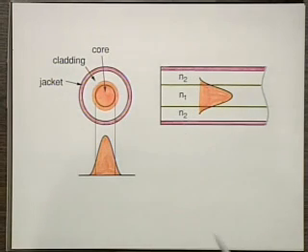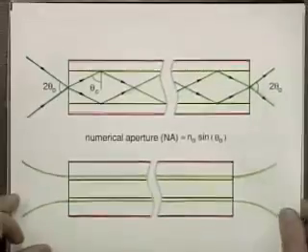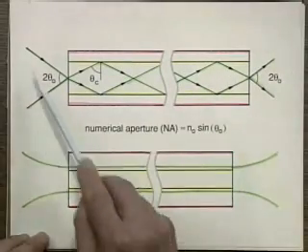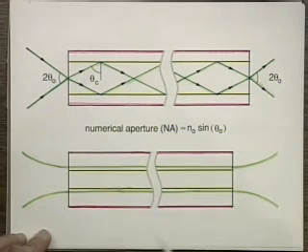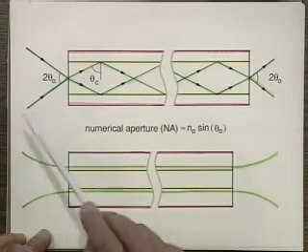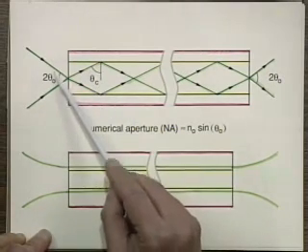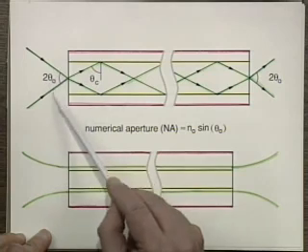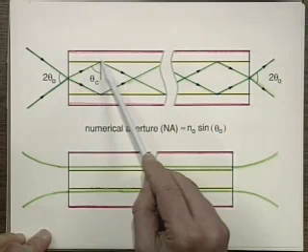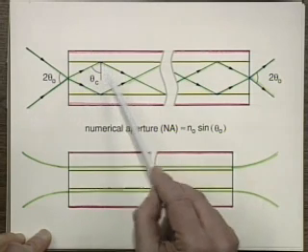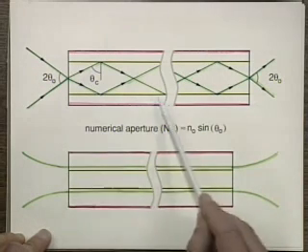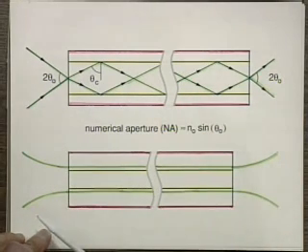Now, how does the light look when it comes out? Let's go back to the ray picture, where remember we said that the angle has to be either equal to the critical angle or bigger, and that determines the acceptance angle going in, because rays of light coming in outside this cone will not undergo complete total internal reflection, and will be in trouble because they won't propagate too far and they'll be attenuated.